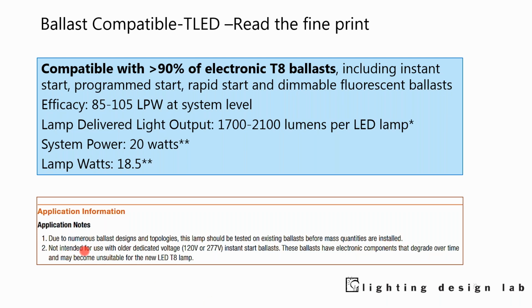Okay, and then it says not intended for use with older dedicated voltage instant start ballasts. Well, usually if you're doing a retrofit, you have older product. These ballasts may degrade over time. Well, all right, and it doesn't make sense to put in a bunch of brand new TLEDs in a fixture with a ballast that's going to fail in 3 years.